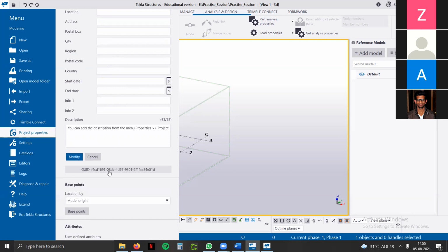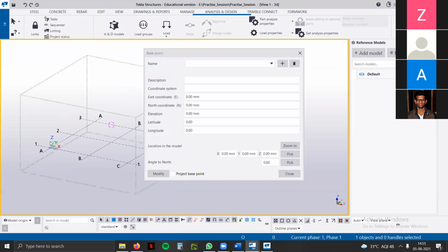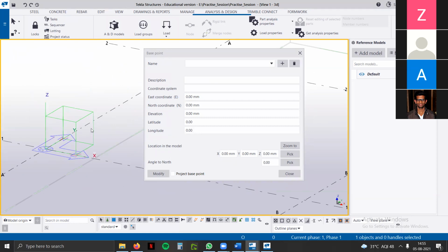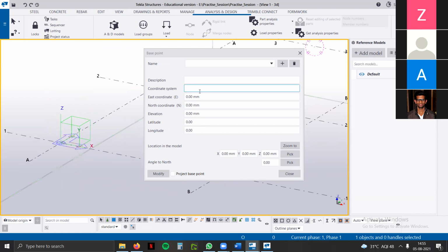And after filling in all that important information, we need to set the location. Like, on real-time coordinates, do we want to start that project, or can we start from the origin axis? If we have northeast coordinates, like from a total station, we generally have the coordinates of the building, the specification of the building, where it is located.